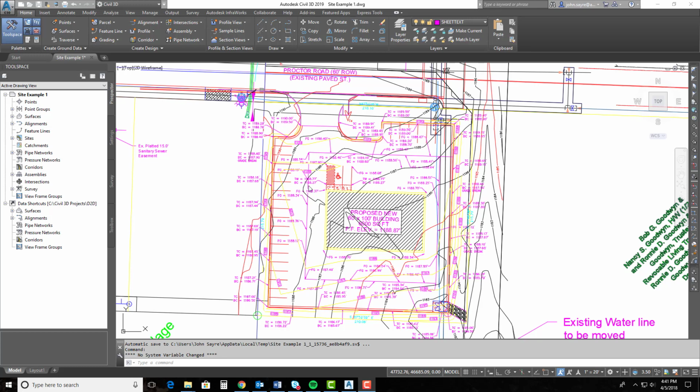So again, we know that this entrance is closer to the property line, and we know that the grading had changed, and we want to be sure that even if we do find the right drawing that has the entrance moved, the grading has been updated also. We know that the existing contours had changed also because we got updated information from the surveyor in the past. So there are several things that we need to check off the list so that we know that things are correct and that the construction staking will be correct.